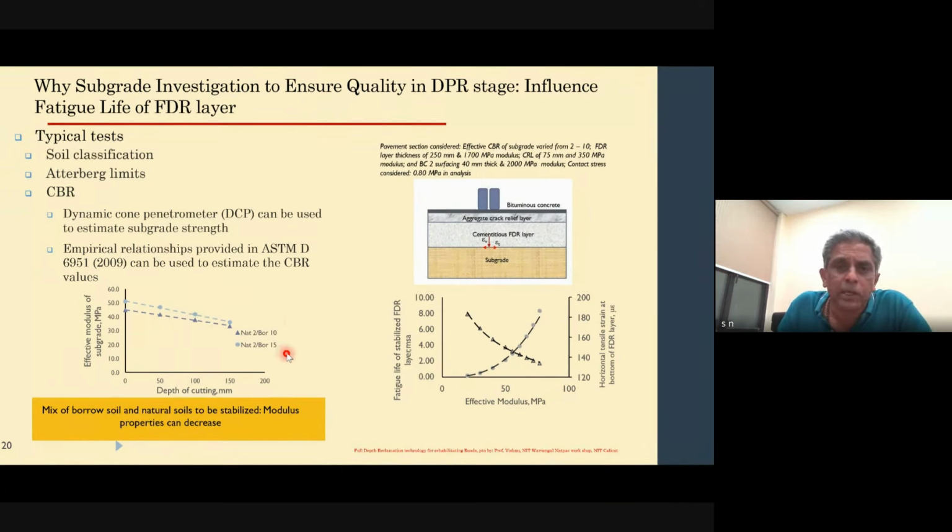So for every given cement percentage, you are going to vary the additive content in that. It depends on agencies. Somebody might be using very small quantities. Somebody might be using high quantities. Let us say the company's recommendation is 4%. So ideally what you do is you have a fixed cement, one of the cement percentages, let us say 4% cement you are taking. You do 3.5%, 4%, 4.5% additive into each one of those.